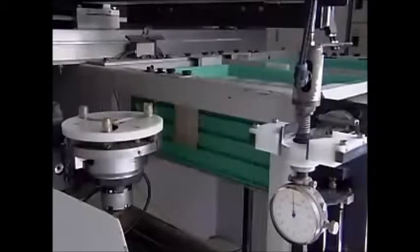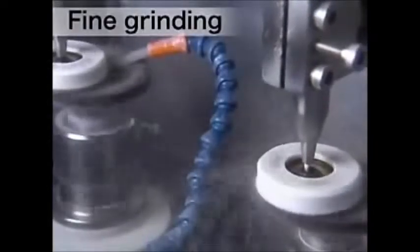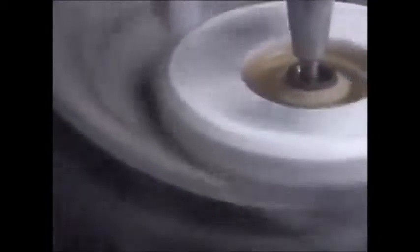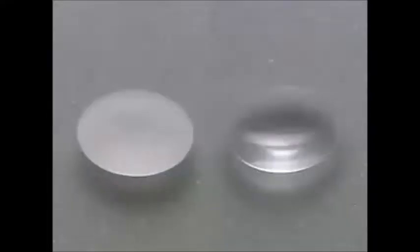Using a curve generator, a super high-speed machine equipped with an artificial diamond grindstone, the surface of the pressed glass is ground until it becomes a curved surface with specified roughness and dimensions. Following rough grinding, the lens is subjected to fine grinding. The surface of the lens is ground with high precision using an artificial diamond pellet platter to attain proper roughness and surface curve. To reduce the time factor and enhance the precision of the polishing step which follows, precision in the order of 1/1000th of a millimeter is required during this step.